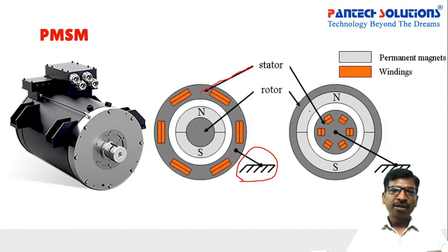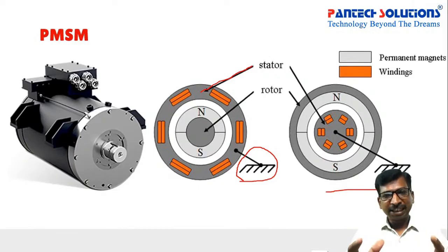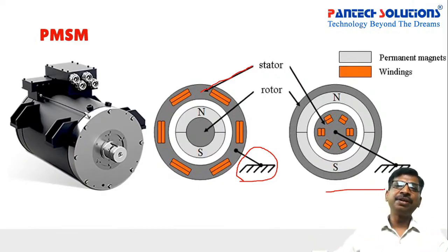See, for example, for electric vehicle applications, we can use this kind of construction. That is the second method. So here again you have one more advantage. These kinds of motors will give you the perfect power, and a higher maximum efficiency if you increase the diameter of the machine. So likewise you can reduce the length of the machine.